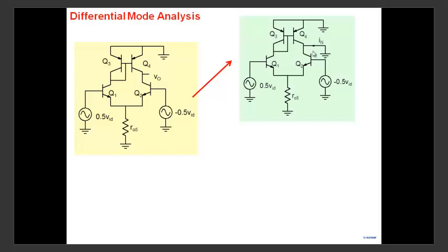Calculation of Norton's current and calculation of Norton resistance. So break it into two parts here, okay? That's what we are doing. We're calculating the Norton's current here, and then we'll calculate the Norton's resistance looking from here. So the whole differential amplifier will become what? A Norton's current in parallel with a Norton resistance. The whole circuit becomes like that, and then it's very easy to write down the gain. So this becomes much simpler. So let's calculate what is IN.